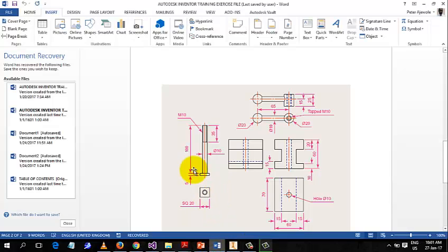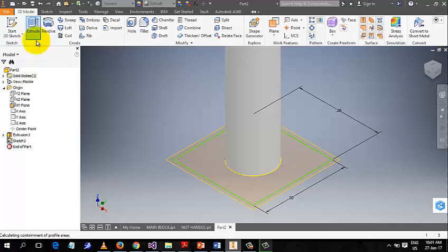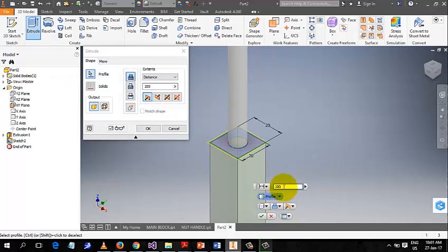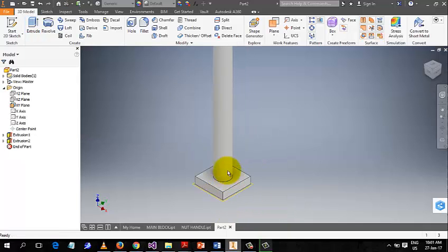Now, what I want to do is to extrude the square head by 5. So if I click finish sketch and click on extrude, click on this face, I want to extrude up, not down. Inventor will remember the last extrusion height. It was giving me 100. I need 5, and that 5 is facing down. I need it up, and I need it to join, not to cut. So you say OK there. So that is the head.